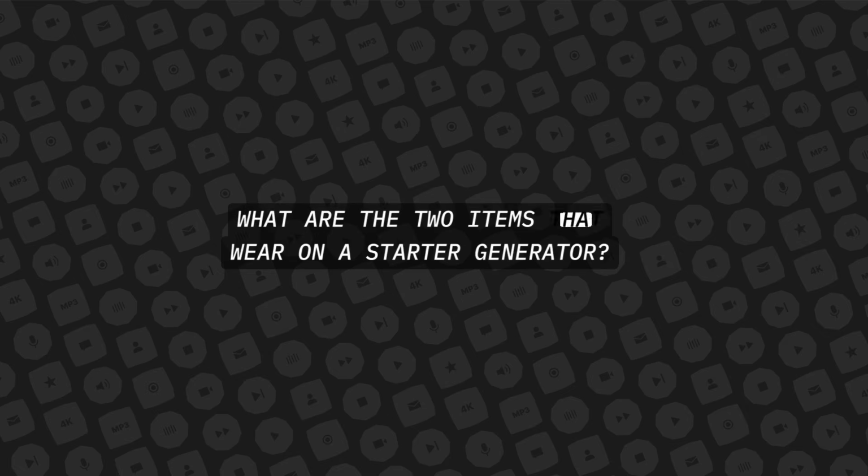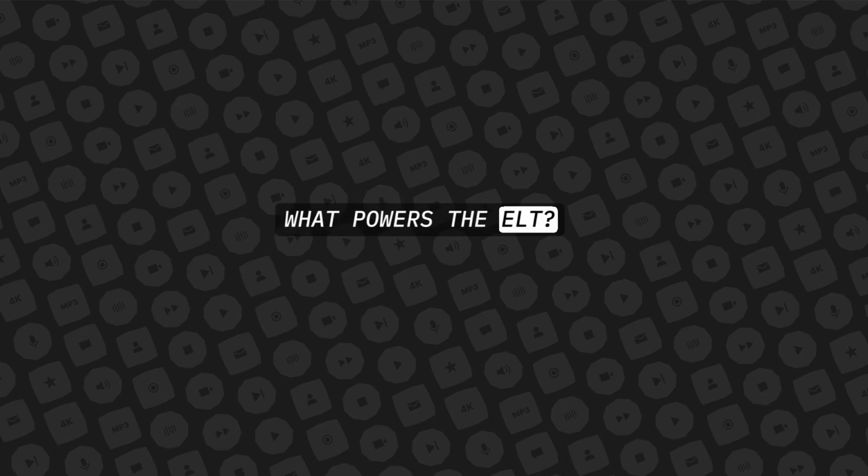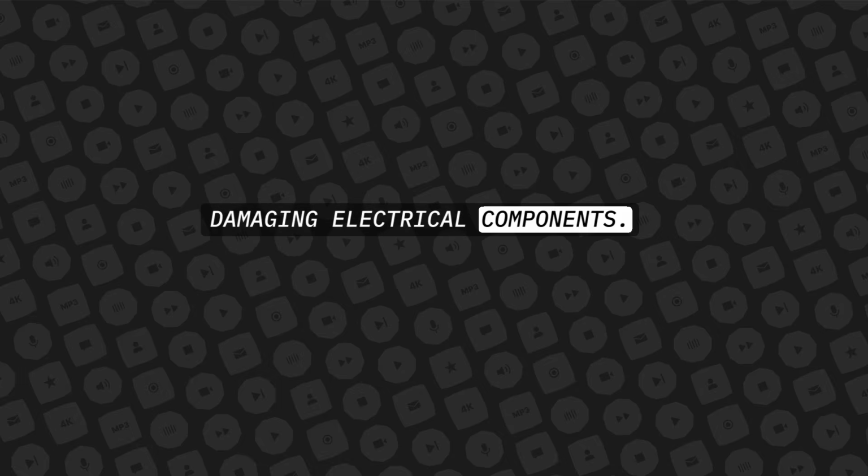What are the two items that wear on a starter generator? The commutator and the brushes. What powers the ELT? The ELT battery. What is the purpose of a static wick? It dissipates static energy from the aircraft to avoid damaging electrical components.